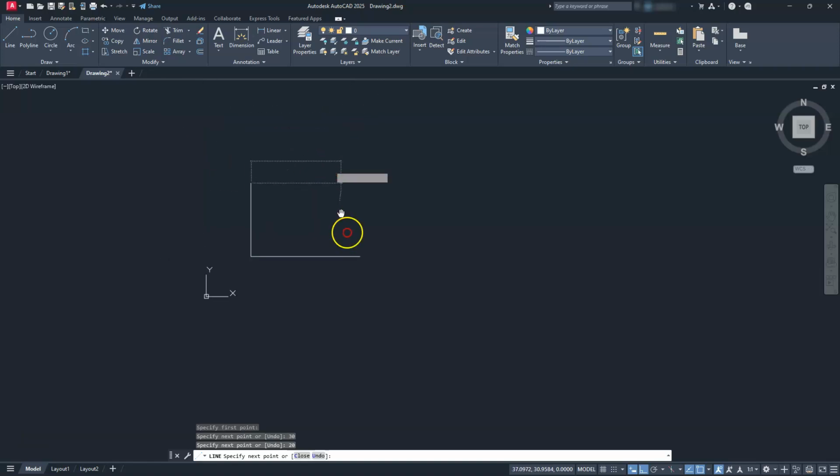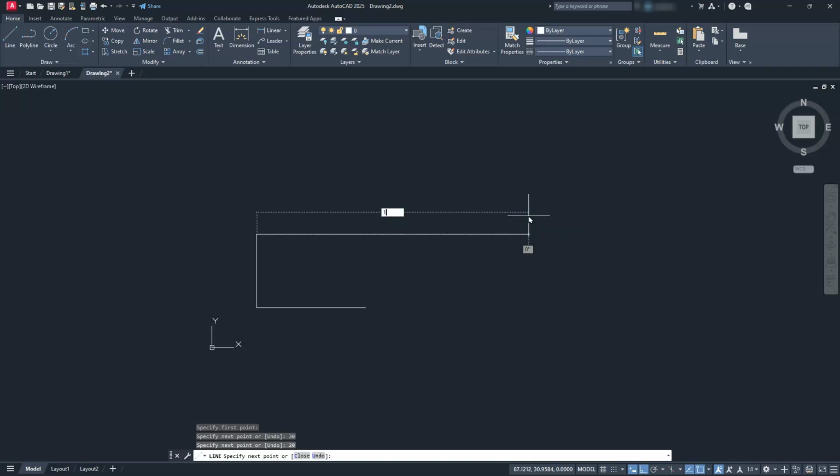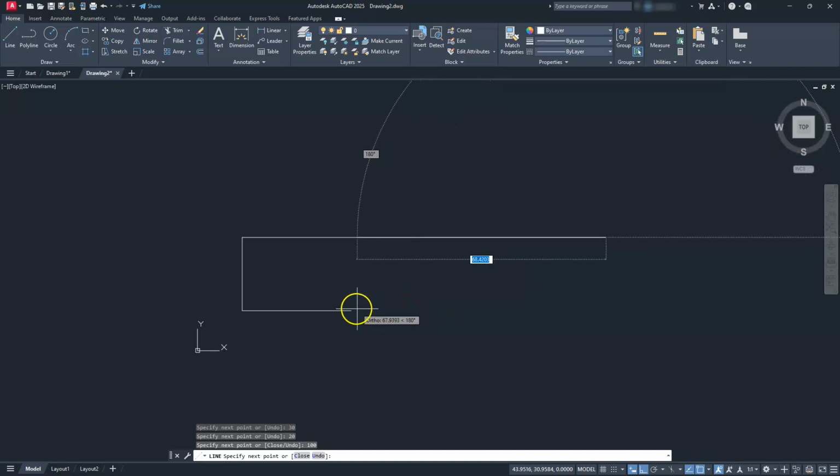Scroll out a little bit, and then I should be able to pan over, right? And now we're going to use that 100 going across this direction. All right, and from this point, we're going to use our polar snaps just to help us out. If you don't feel like typing, this is one of those things that can help you out a lot. I shouldn't say polar tracking, sorry, O-snap tracking. What I need to do is just touch this endpoint, and then when I bring my cursor down, you'll see that it'll lock up on this point. Go ahead and do a left click here.